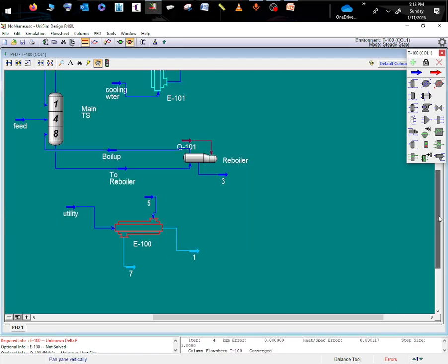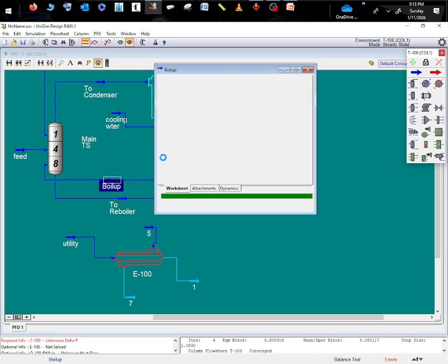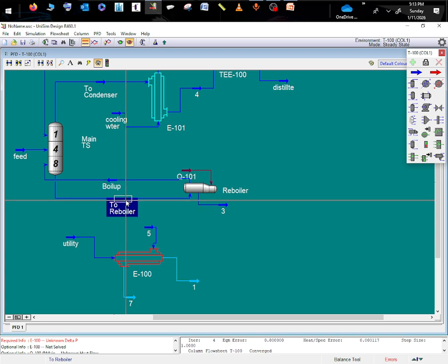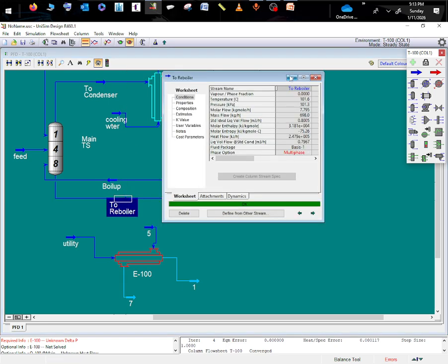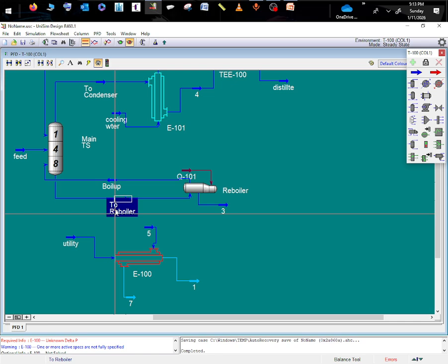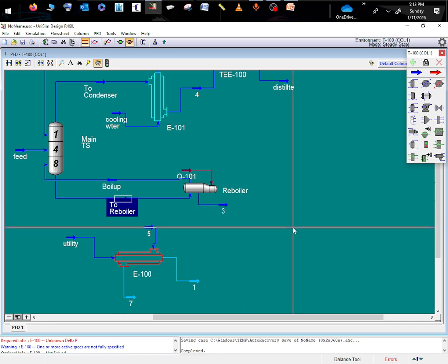And so if you take a good look at your boiler composition, you find it actually has a higher benzene concentration than the reboiler part. This is actually a result of the heat added to your kettle reboiler here. The heat added vaporizes the more volatile component, that is benzene. So it concentrates benzene. It removes the mass of benzene from this liquid phase stream, so we have a more concentrated toluene stream here.